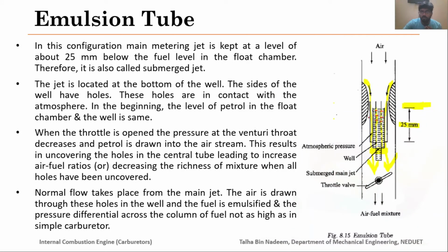Air will now start moving through these uncovered holes into the main tube, where it will be mixed with the fuel, thus forming an air-fuel mixture, an emulsion sort of mixture.